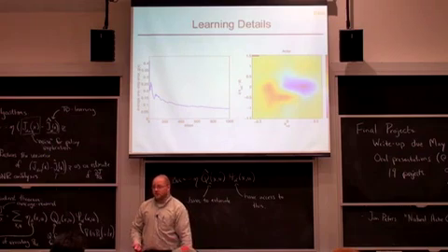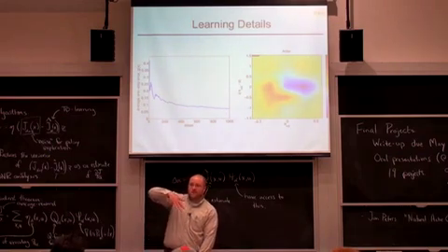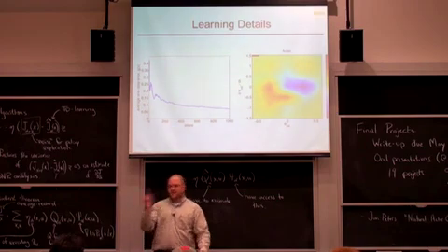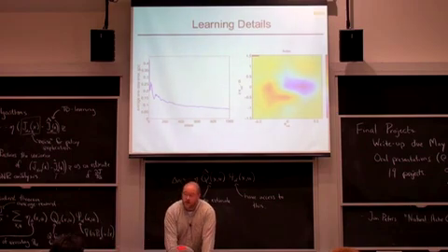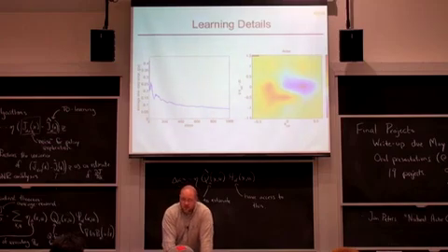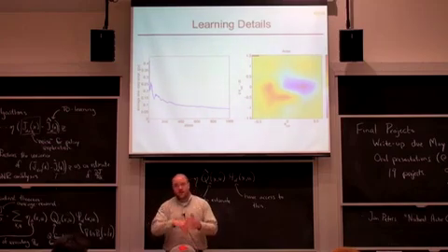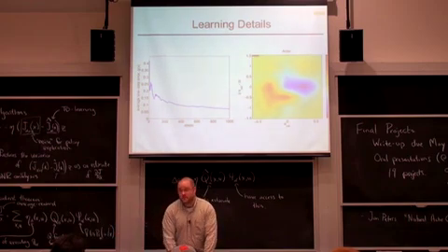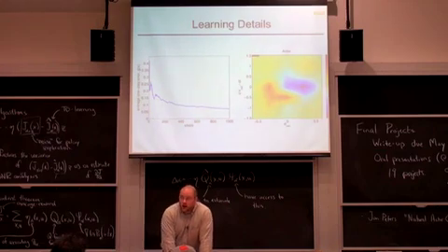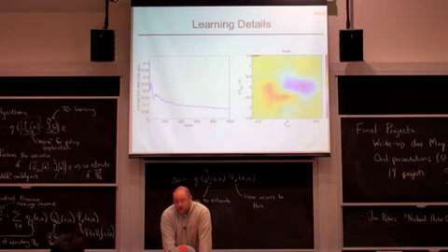But it actually learns fine when it starts off unstable. The way I tested that is if the ramp was very steep, then it starts oscillating and falls off sideways. So just to show that it could stabilize an unstable limit cycle with the same cost function, it's absolutely no different. I showed that it stabilized that, and it just meant I had to pick it up when it fell down a bunch of times. But the same algorithm works for that. So it's not really the stability that it was counting on. That was just experimentally nice. The big clown feet and everything were because that's how I knew how to tune the passive gait, right? And in the passive walkers we work on these days, you'll see point feet because I care about rough terrain now, and those clown feet are not good for rough terrain. So we could try to get rid of that.